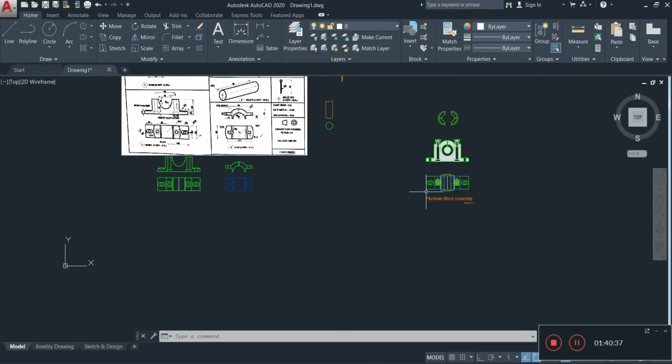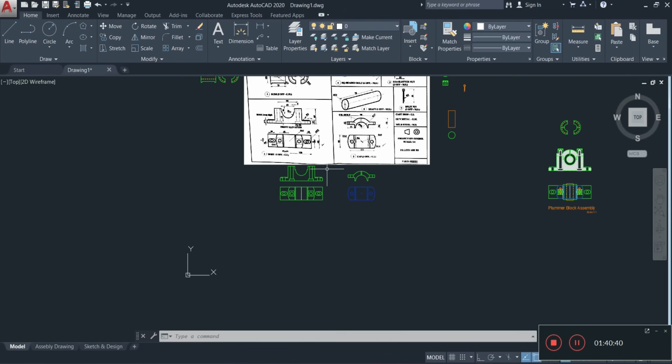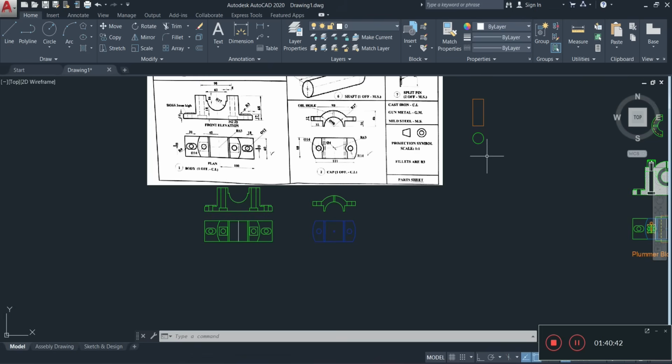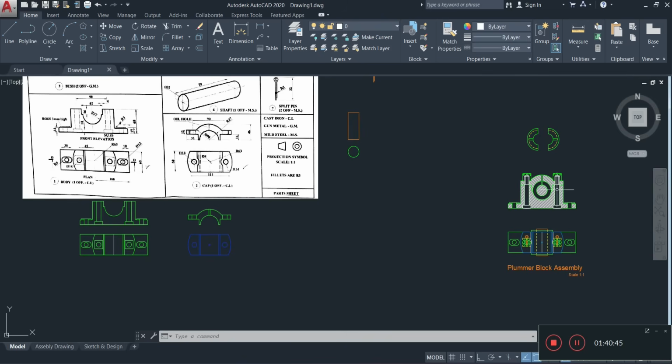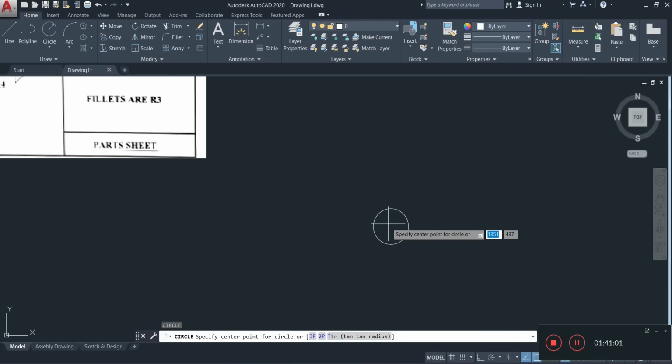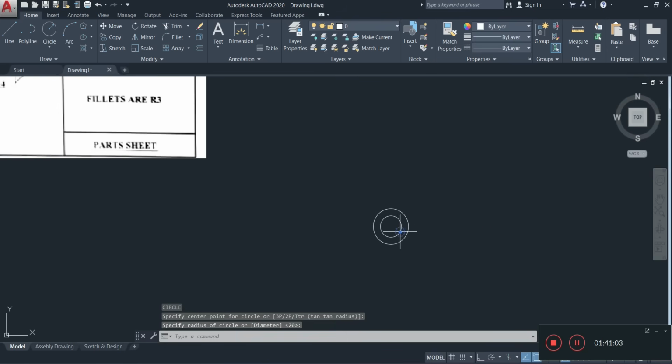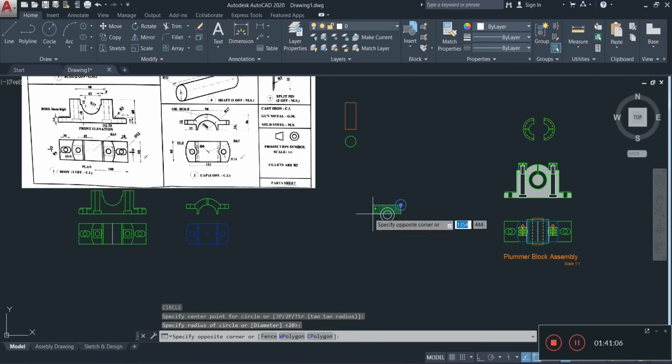Alright, and we're going to sort out our little parts list right now, and we're going to draw our orthographic symbol. Since we copied and did the whole elevation up top, plan below, it is basically our first angle, so we're simply going to reproduce this here. So we're going to go circle, click, let's just use a suitable measurement there, circle again, click, like that. Let's copy this here, CP, and let's place it right here on the corner there.